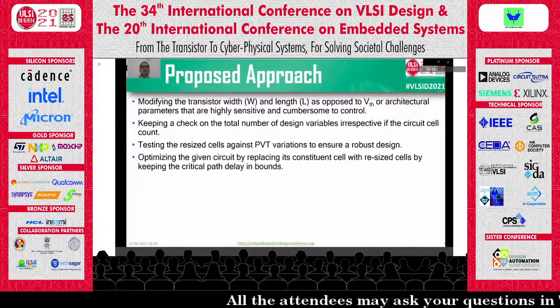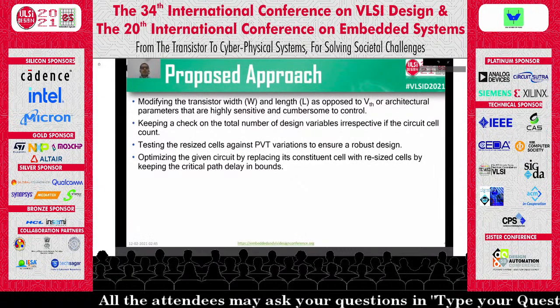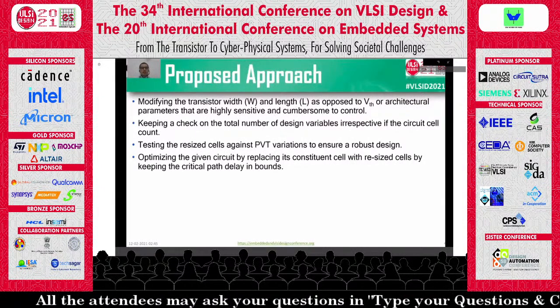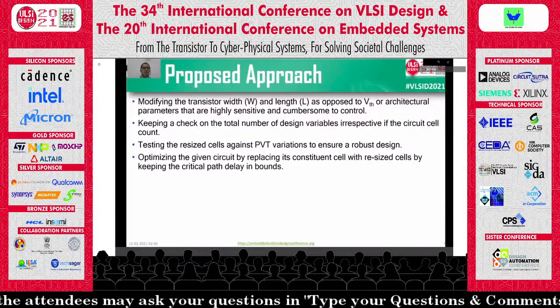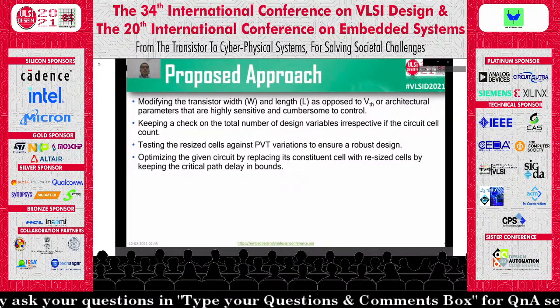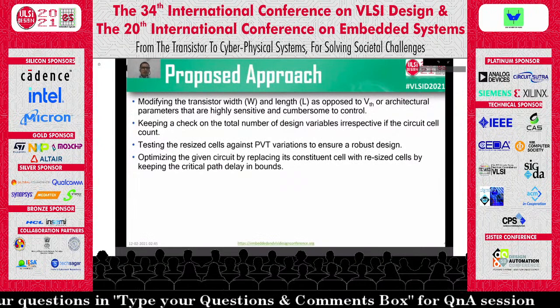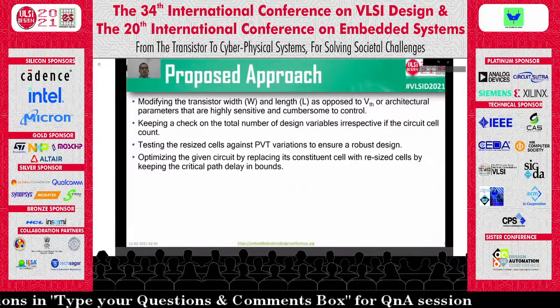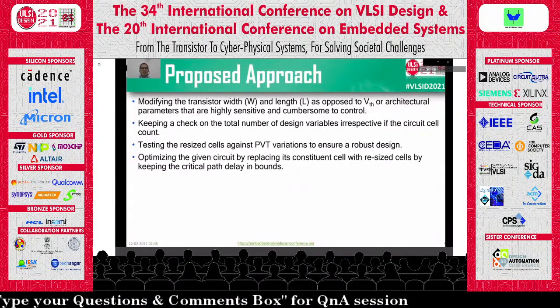Also, the adverse effects of certain processes, such as changing the threshold voltage by altering the gate oxide thickness, which might lead to an increase in the gate leakage current, can be avoided. Next, we verify the performances of our optimized cells.